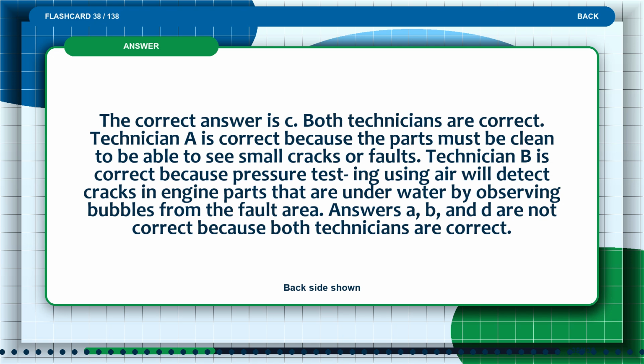The correct answer is C. Both technicians are correct. Technician A is correct because the parts must be cleaned to be able to see small cracks or faults. Technician B is correct because pressure testing using air will detect cracks in engine parts that are underwater by observing bubbles from the fault area. Answers A, B, and D are not correct because both technicians are correct.